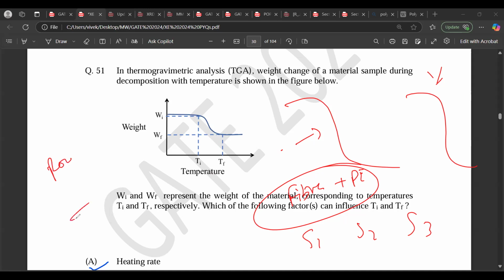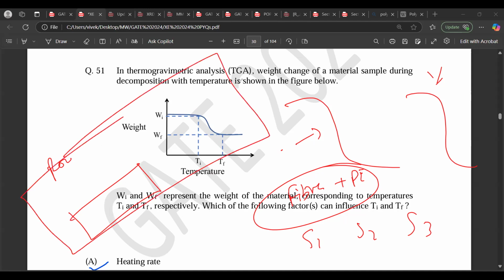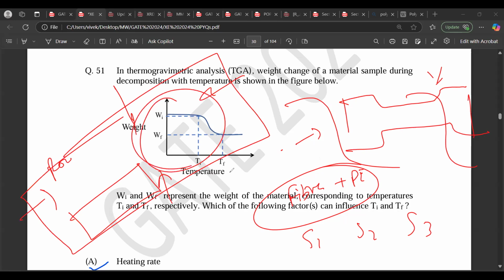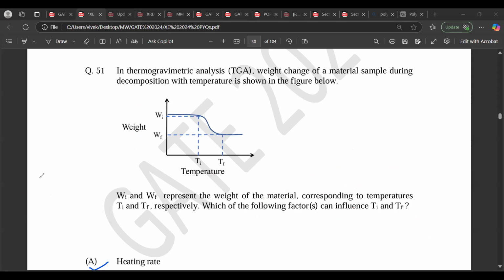You have to have the same sample size, because if you change the sample size, your elongation and other mechanical properties may change. So there is a fixed standard size, right? So sample size is one factor, and also strain rate, at what rate you are elongating, and in the case of DSC, what heating rate you're giving. So there are many factors that you need to learn. If you have not read it, please read it. It doesn't take more than 10 minutes to learn for each testing.